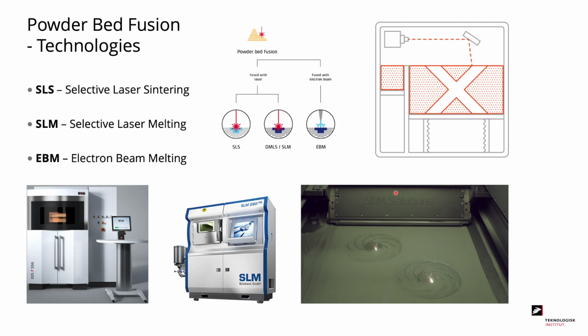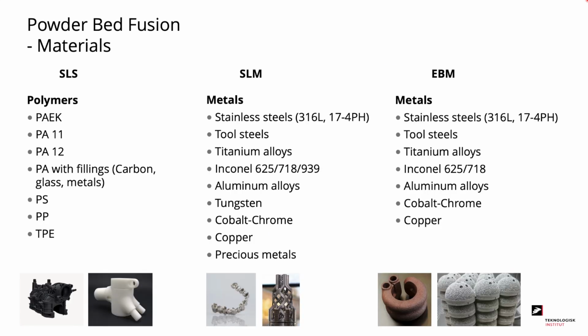We can see how we are applying our laser to the powder bed. We do this one layer at a time and build up our part. In essence, the technology is very similar to SLS and EBM. Let's have a look at the available materials for the powder bed fusion process.